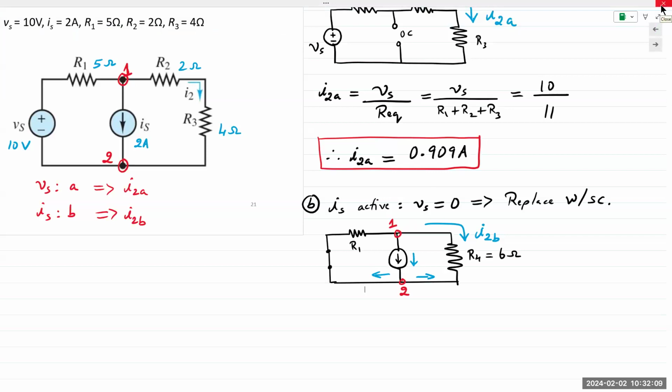But in real life circuits, when you apply this kind of principle, even in problems, take a few seconds, look at the circuit, see how it is changing. Because of the open circuit of current sources and the short circuit of voltage sources, connections are either made or broken, and so the circuit changes. So again, take a few seconds and look at the circuit first, and then begin your analysis.